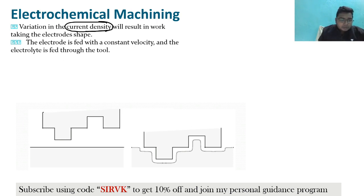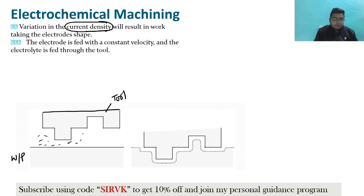Now try to understand here. Basically this is your tool. Suppose this is your tool, and this is your workpiece. Clear? So earlier the workpiece is flat. Now you want to make this kind of profile, this kind of cavity in the workpiece. So what you will be doing? There is an electrolyte that will be flowing here. Now when you move this tool down, then these kinds of cavities will be formed, you can see here, and hence the machining is done, and this is the machined surface, right? So in this way you are actually getting the machining done.